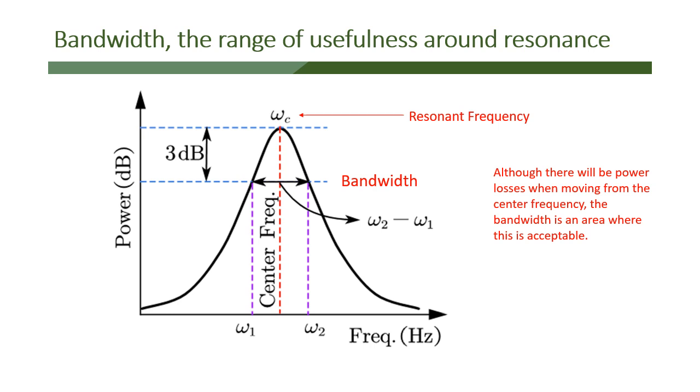But you can be tighter. You can be much tighter. It all depends on the design of the antenna. There are benefits to being tighter in this bandwidth, and there are some benefits to being wider in this bandwidth. But again, it also is a trade-off between losses and energy released that you have to make. But all we have to do for this course is understand that every antenna has a center frequency that it's optimized for, and there's an acceptable bandwidth on either side of that center frequency that we find usable for most of our transceivers.